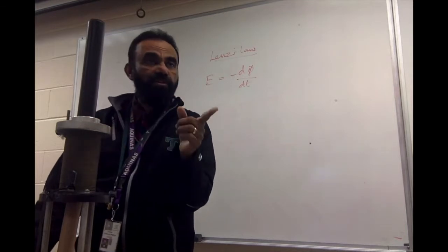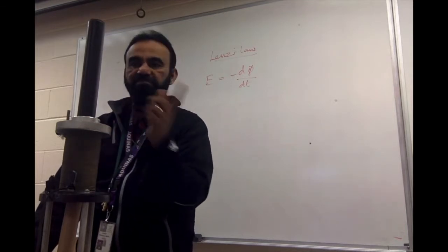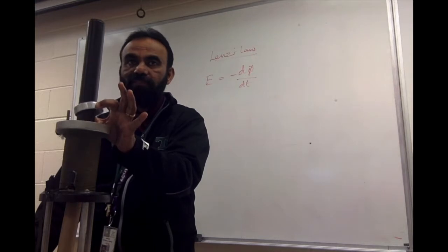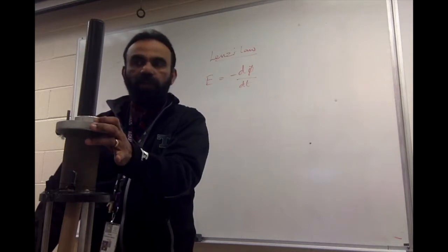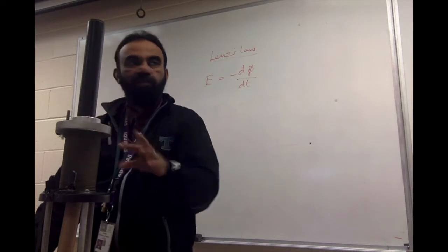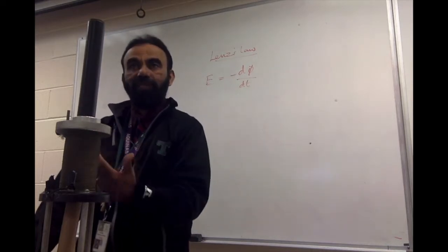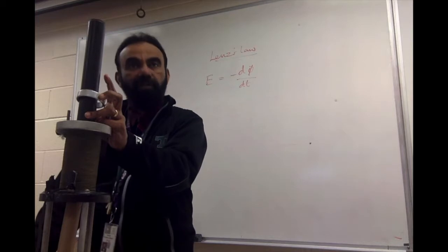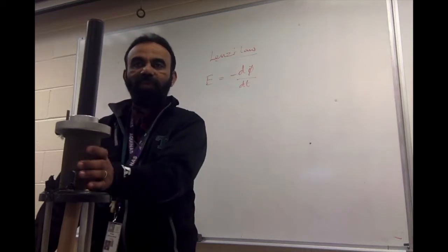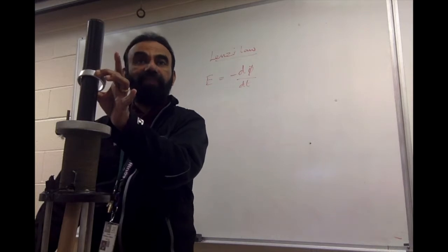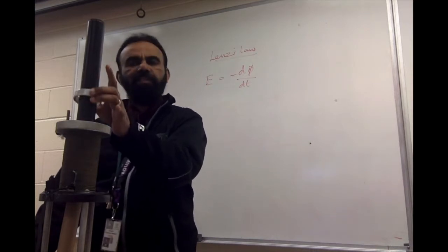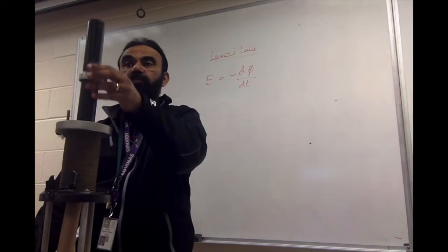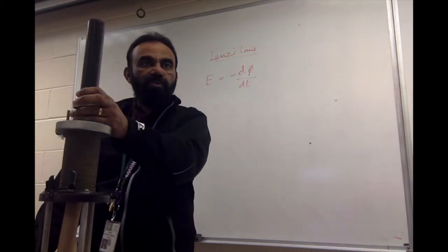All right, so since it is alternating, first the magnetic field is possibly going that way. So the induced current is going to flow the other way in this so as to produce opposition, correct? And opposition means it's going to be pushed out. Now the cycle changes. The current here is now going to flow the other way around and create a magnetic flux the other way, but this current is also going to flip, creating an opposition again. So when current is flowing here, induced current is also going to flow here alternating, in such a way that there is opposition all the time. And that's the reason why it can experience that huge force, even beating gravity, strong enough to take it out.